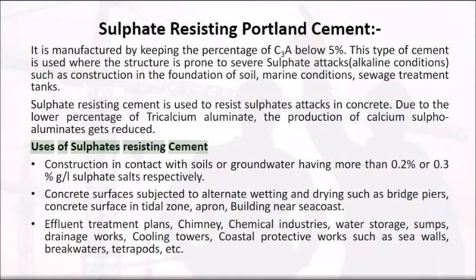Uses of sulfate-resisting cement. Construction in contact with soils or groundwater having more than 0.2% or 0.3% g/l sulfate salts respectively. Concrete surfaces subjected to alternate wetting and drying such as bridge piers, concrete surface in tidal zone, apron, building near seacoast.